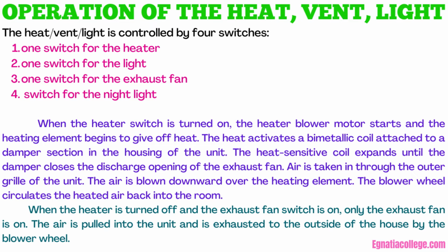When the heater switch is turned on, the heater blower motor starts and the heating element begins to give off heat. The heat activates a bimetallic coil attached to a damper section in the housing of the unit. The heat-sensitive coil expands until the damper closes the discharge opening of the exhaust fan.